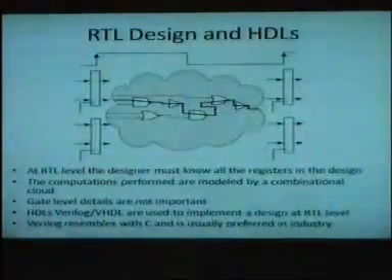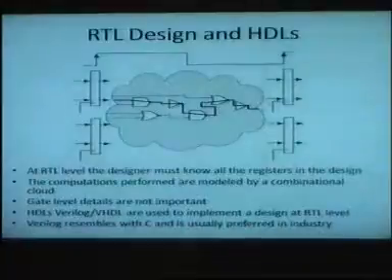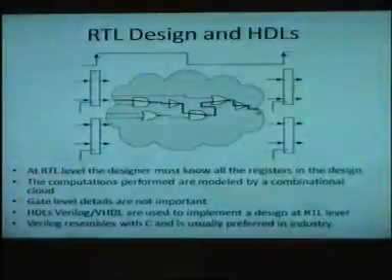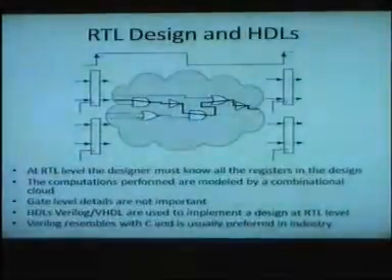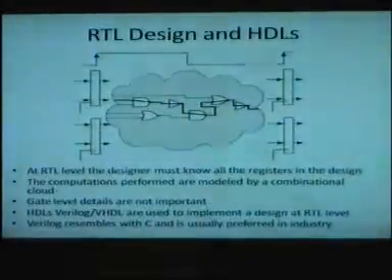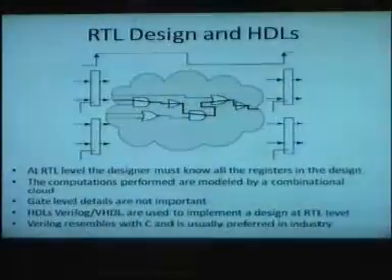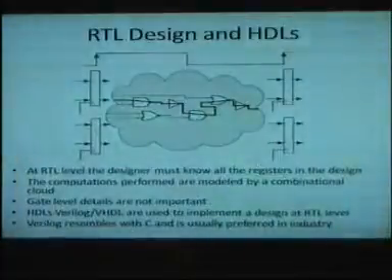The only thing that will happen is that you will be sampling something which is not stable. Maybe you sample a wrong value. It is 0, it needs to be 1 once it settles down, but a clock comes and whatever value you have here goes to the output of the register. So usually once you synthesize something and try to run it at a higher clock, it will run, but it will give you all garbage values, especially on the paths which are violating timing.